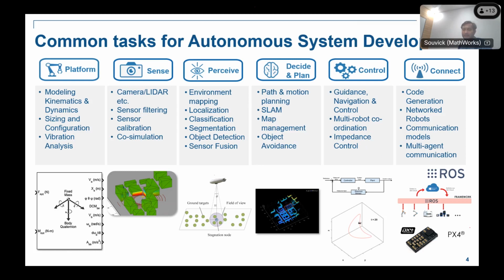How does that work? If you have some camera connected to, say, a Raspberry Pi, if you have some sensor connected to some other controller, and if you have something else connected, all these things, the common communication platform can become ROS. You can have a MATLAB node as a ROS node. You can have the hardware as a ROS node. And once we integrate all these things together, ROS becomes the common communication platform. Like today we are talking in English, ROS can be that integrator, that middleware or communication platform through which all these different sensors and algorithms can talk to each other, right?